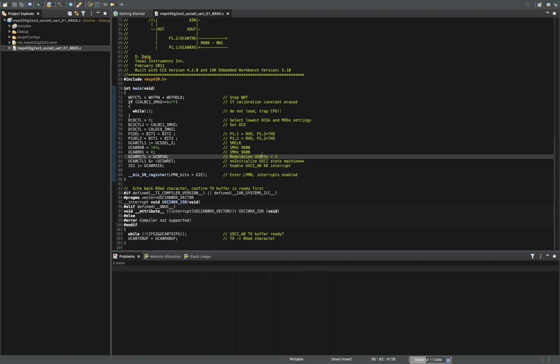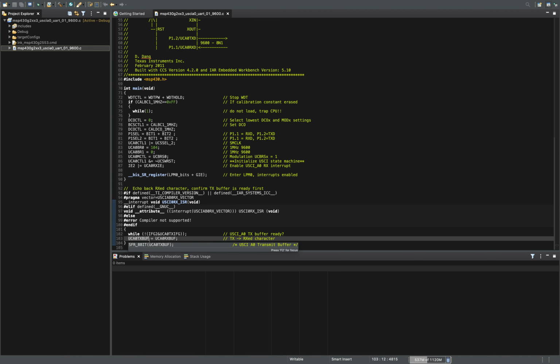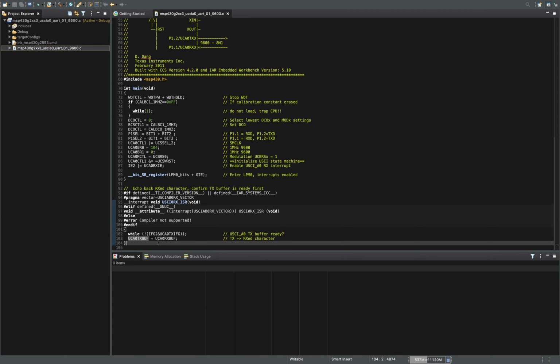We're also going to tell the peripheral that controls the UART interface, hey, I need you to use the submain clock, and we're going to set some dividers here to set the right baud rate and what type of modulation we want. And this example also uses interrupts. So essentially what this is going to do is do all of our configuration and then sit here and basically say enable all the interrupts, I'm going to go to sleep now. So the only time that this code will actually fire off, and I'll show you this with a breakpoint pretty soon here, is when we receive something from the other device. When it does, it'll wake up and basically say, are you ready to transfer data yet?